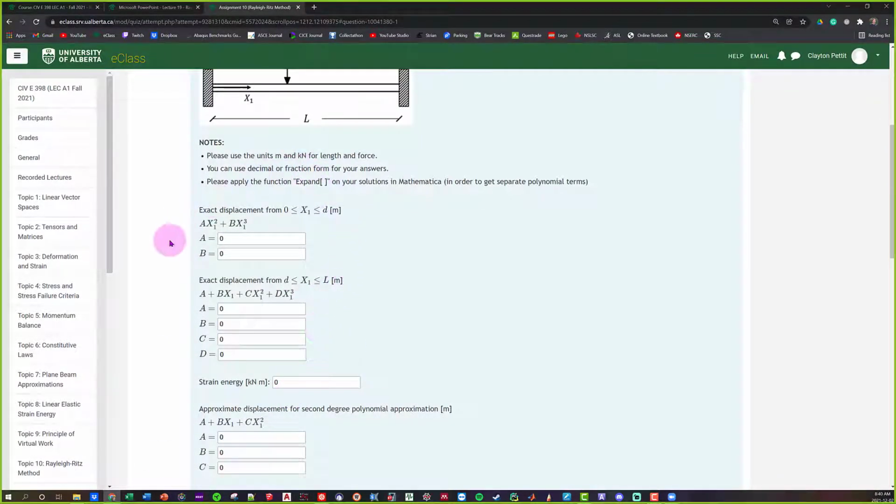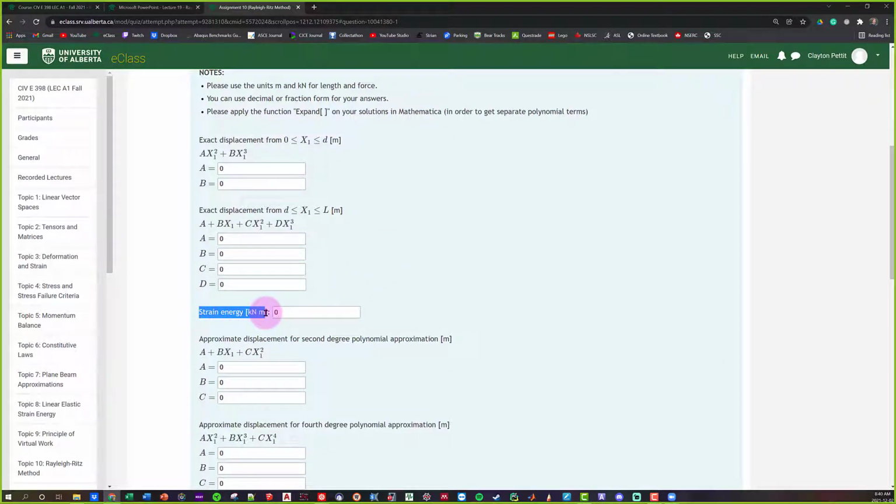So the next part, if we were to just go down the entire question, it says, what is the strain energy? The first trick, not trick, I'd say more of a trap, is that students will go to the strain energy section of the notes, they'll find the equation, and then they're going to try and play around with it. But as you're going to see, if you want the total strain energy from that section, you need to integrate over the beam.